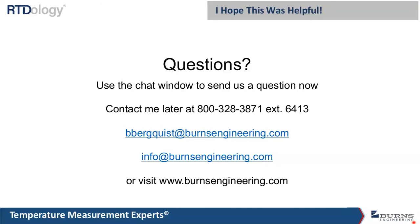Just a comment, which I think is a good one from Jody. This kind of goes back to the dual. Some transmitters do have the capability to have two inputs. One will be the default as the output signal until the other one goes out, and then it can switch over automatically. So there are some transmitters that have that capability to have two inputs, either for redundancy, safety, and/or sending the signal to two different places.